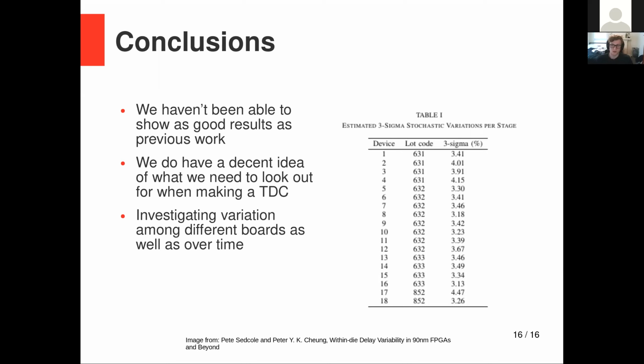Compared to the 220 we're seeing with these inverter gates, that's massive. And he can get extremely precise control. He was using essentially that tap delay line circuit that we showed, but just using the carries instead of that. Like we could see graphs of just these pulses that are only a couple picoseconds in width, and we could just see them. It's pretty cool.